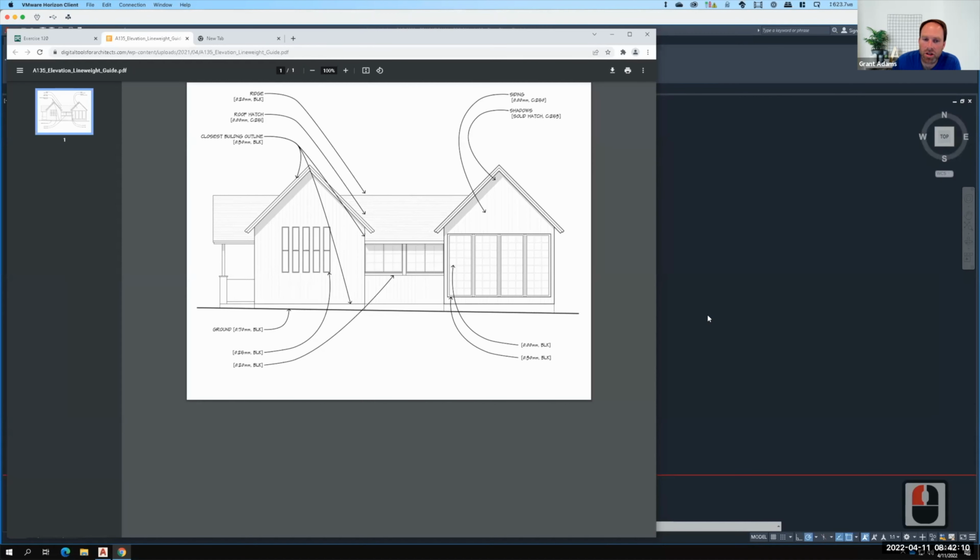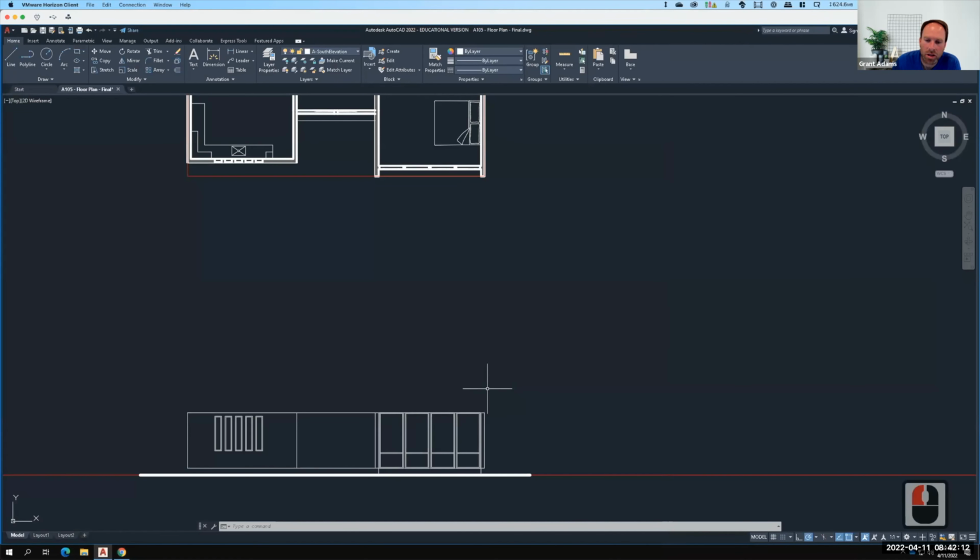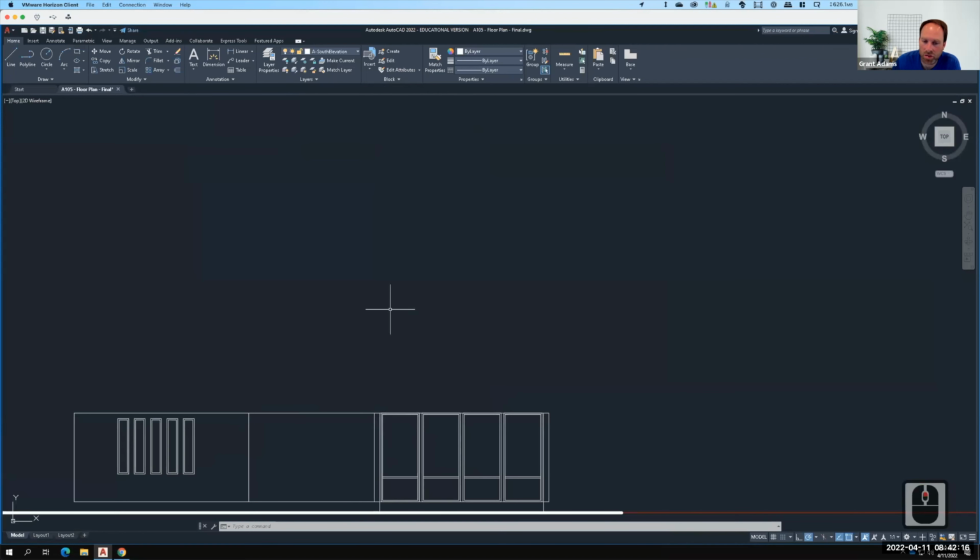But you have a decision to make, and that decision could be to have a flat roof. It could be to have a pitched roof. And that's going to change how you draw your overall building. If you are having a flat roof, for example, it may be something as simple as drawing, right? A flat roof would probably want to be at least 12 inches thick.